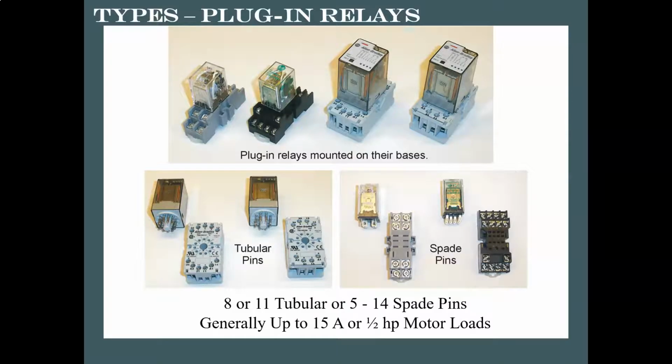Okay. So here is your plug-in type. You might recognize this from first year. They usually have, as you can see here, it's like an ice cube with a bunch of spades in it, and those spades or pins plug into a base, right? And they can only plug in one direction, so those pins are going to go to the proper terminals, right? And these terminals are going to be labeled on the bottom or on a legend telling you what terminal is for what purpose, like the common terminals, normally open, normally closed, etc.